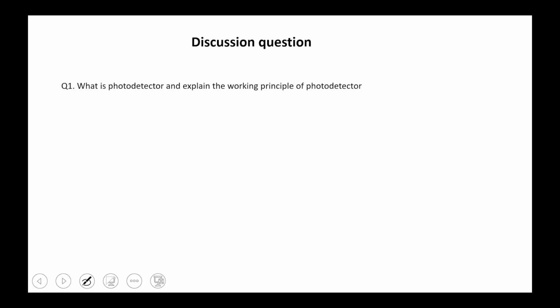Sir, it depends upon what kind of photodetector we are using, either a simple PN photodiode or a PIN photodiode. In a PIN photodiode, as the depletion width of the intrinsic region is larger, the carriers move with the drift velocity, so the response time is less.